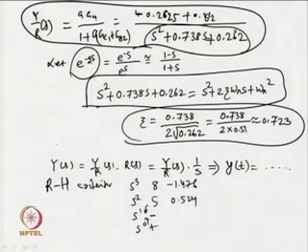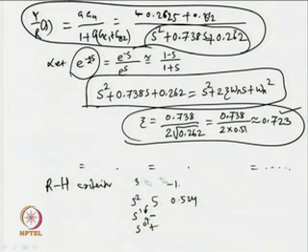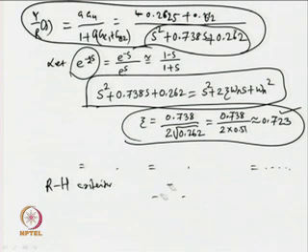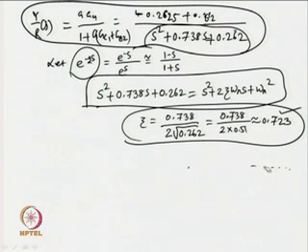So, this damping ratio xi gives us the information that we get an underdamped response for the closed loop control system. Now, when the input is unit step reference input, at that time the output of the system will be underdamped response, because the damping ratio is less than 1, that is 0.723. What other information one can obtain from the closed loop transfer function of the system which has got now both the feed forward and feedback controllers?